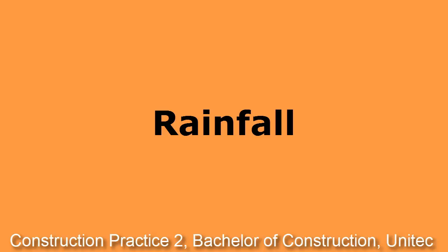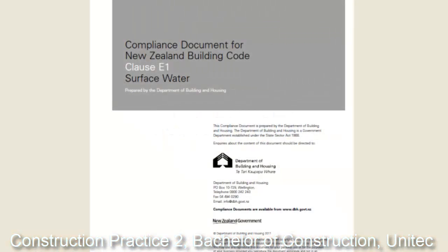The rainfall intensity and how this can affect the building at both low and high intensities. For example, low intensity is considered normal rainfall, and an acceptable response to this is to design flashings, drain joints and roof overhangs and gutters and more. High intensity creates increased load on stormwater systems and flash floodings.